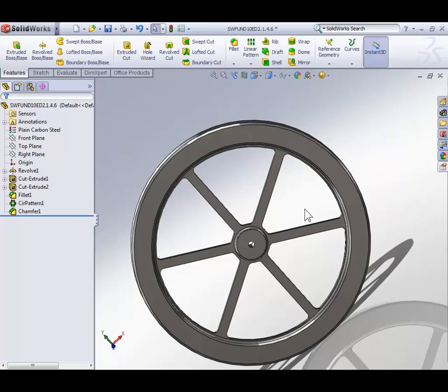Now, the other thing that we did was we entered a number in millimeters, and SolidWorks automatically converted it to inches. This is important to notice, because everything that we do in SolidWorks is in full scale. When we work with different units, all we're doing is changing the dimensions that are displayed. Then, the drawing merely takes the full-size SolidWorks model and scales it down to fit on a piece of paper.